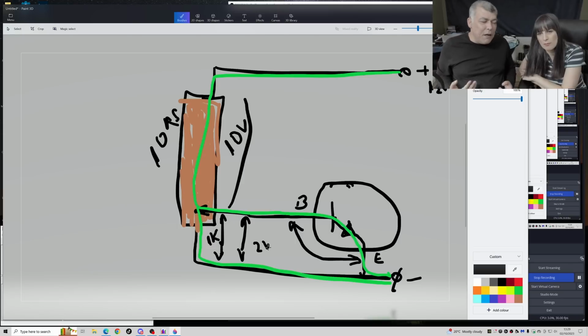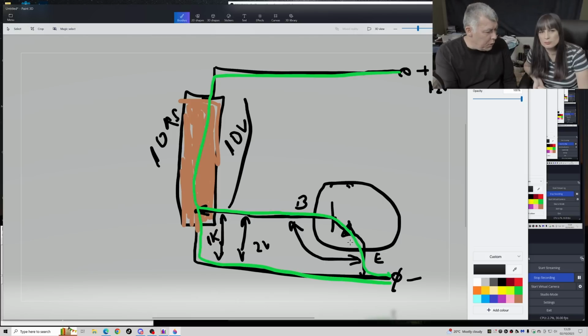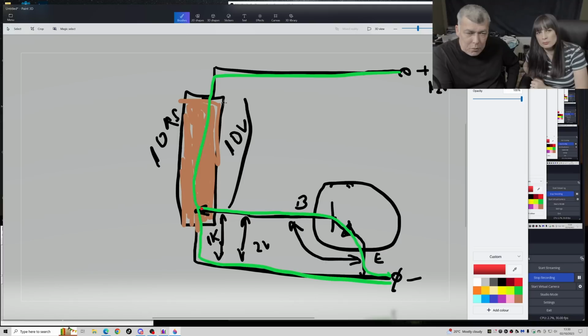But you understand, that's the thing. What will happen if you have resistance in parallel mode? What will happen with the total value? We spoke about how you connect the resistor in serial mode and parallel mode. It will be lower, so I will not have 1 kilo ohm, I will have less. That means I will have less voltage here. That's how this is working. Actually, this schematic is not right, because when you adjust and move this arrow, you'll have too much current or too much voltage on the transistor base, and you can burn the transistor. So you understand?